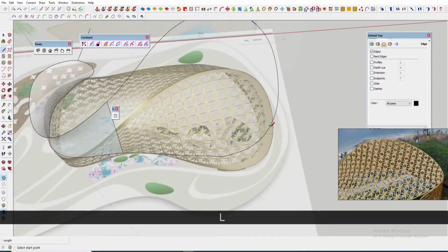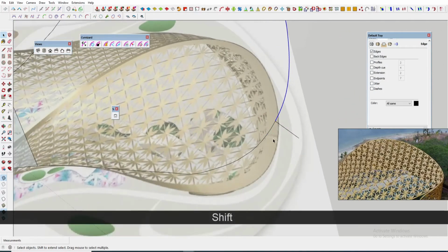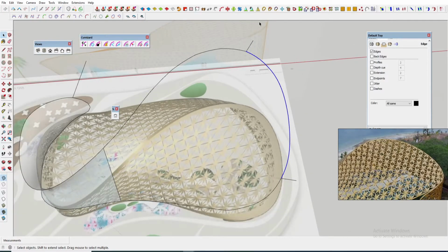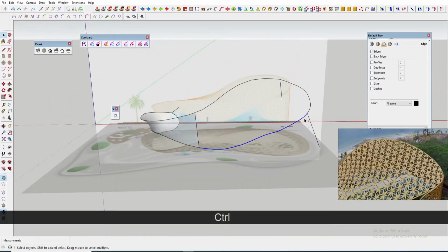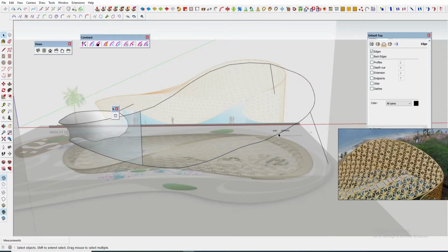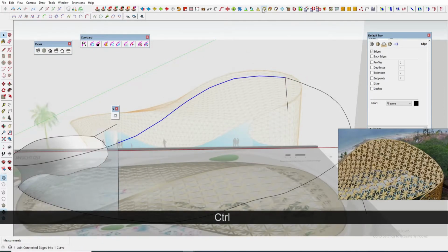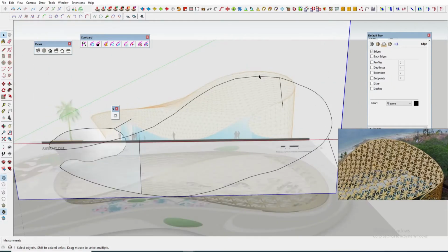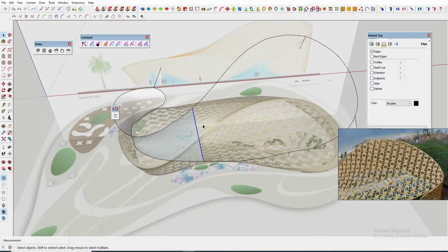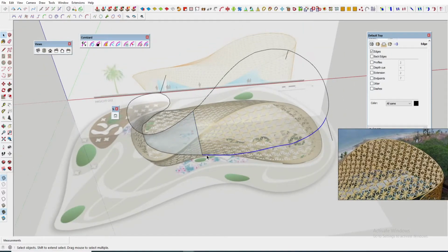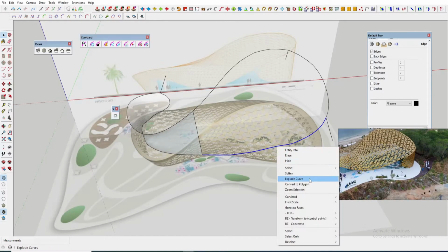The Flowify plugin requires 4 corners. So I'm dividing it into 4 parts. The whole right side curve I am welding, so it will be like a single line, a single curve. The bottom and top also I am welding. So all the 4 edges have to be welded. Now I am using the BZ Powerbar polyline segmenter to give all the segments equally, meaning top and bottom have to be equal, and left and right have to be equal.